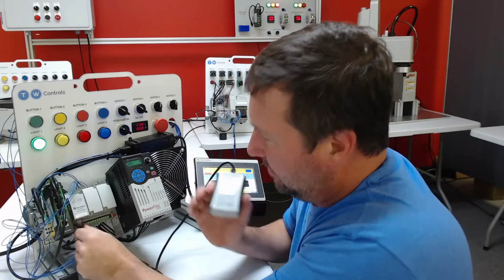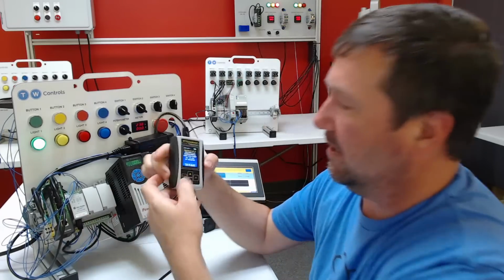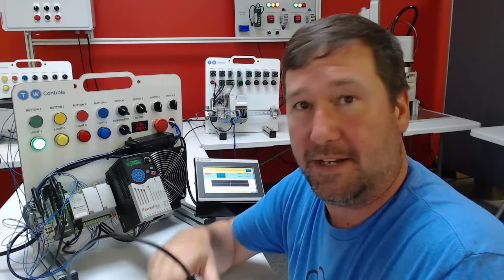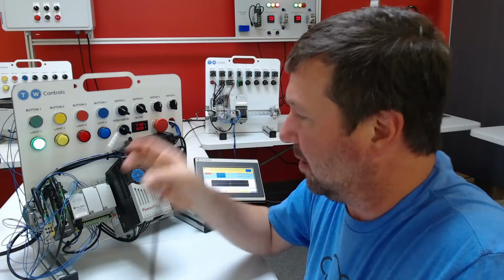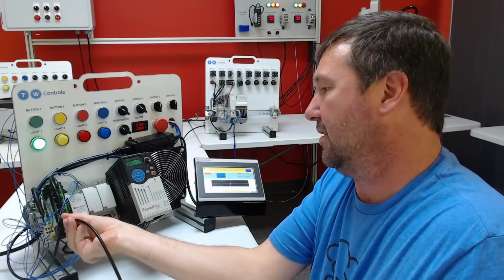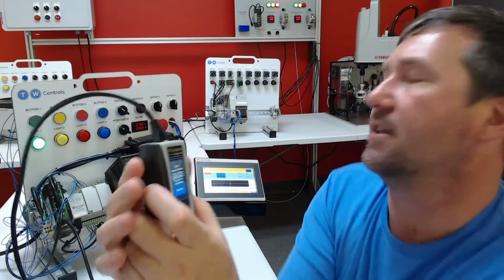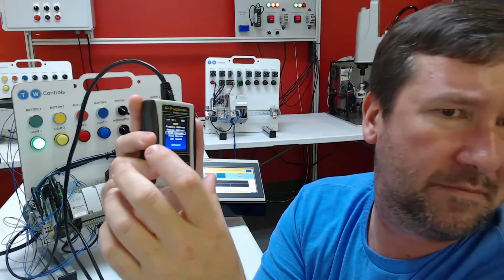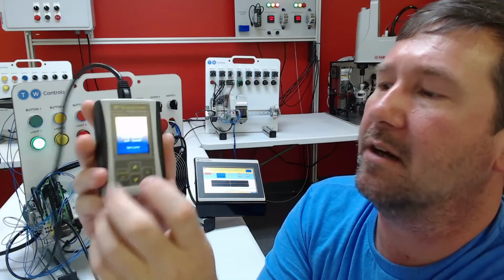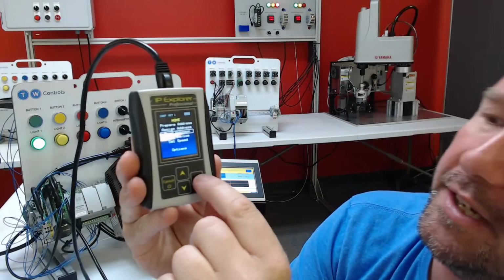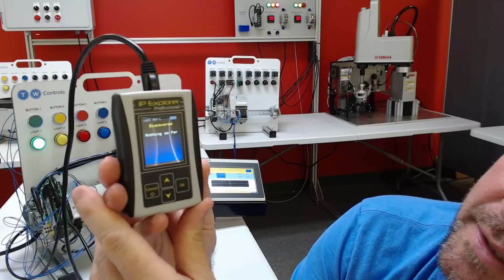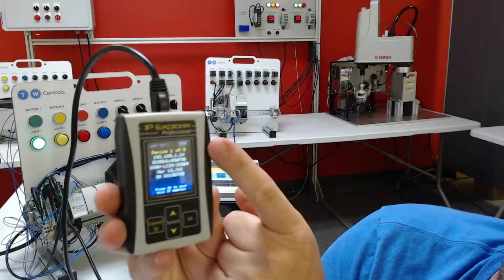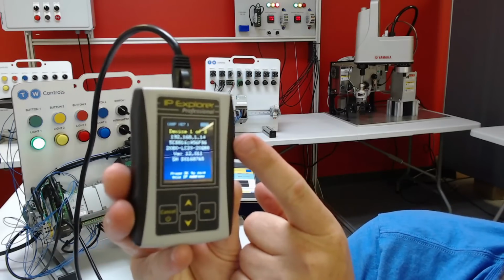Now, one other neat thing you can do is, let's say we're trying to figure out what IP address we should set our PC at, or what all is on this network. You can actually plug it into an Ethernet switch. I'm not sure what all is on this network. Well, most of the PLC lab is shut off right now. But now if I go to read unknown, all right, it's discovered 8 devices. See, I'm reading that top line right there. Hopefully that focus is okay.